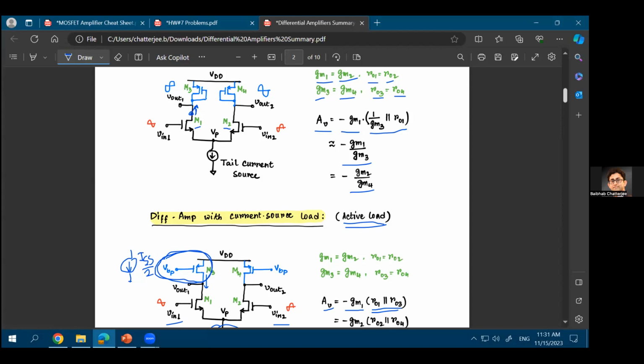So yeah, that's a good point. It's not negative, it's the way you represent it. So this is a PMOS. For PMOS, the formula is not VGS minus VT, it's VSG minus VT, or the absolute value of VGS minus VT. As I said, the best way to consider these scenarios is that you always take the absolute value of it. So then it would end up being the same GM. Exactly. Whenever you see a PMOS, use the same formula that you use for NMOS, but with the absolute sign.